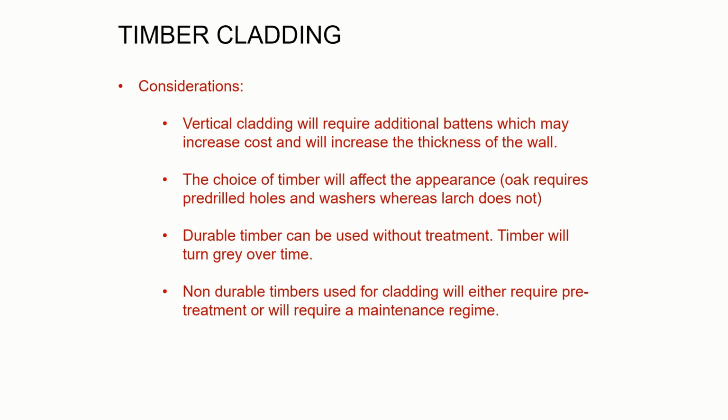Whereas non-durable timbers usually need a paint or a stain or some other coating, and that needs an ongoing maintenance regime. So if you're using a non-durable timber that's got a stain to it, then every 5 years you're going to have to redo that. So that's a consideration at the start.